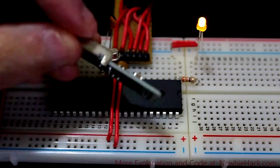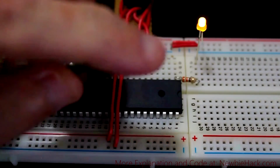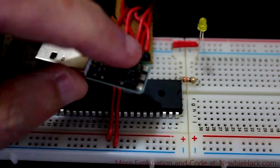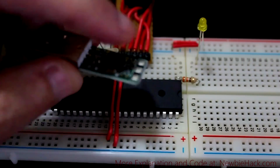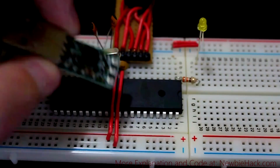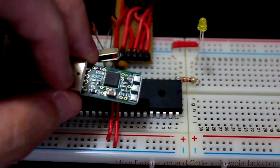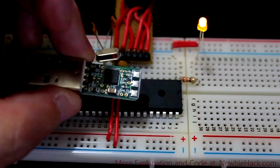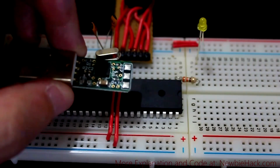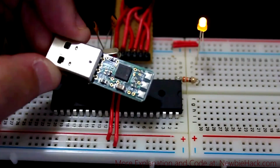I have a little circuit board here. It plugs into the computer through the USB, and what it does, this is a USB to serial interface, and we'll plug this into the TX and RX lines of the computer. I'm not going to get into using the COM port on a computer because those are essentially obsolete. I don't know of any computer that has them. They may be on the motherboard, but that is a little bit too much to deal with. So I'm going to go the USB route using an FTDI 232.